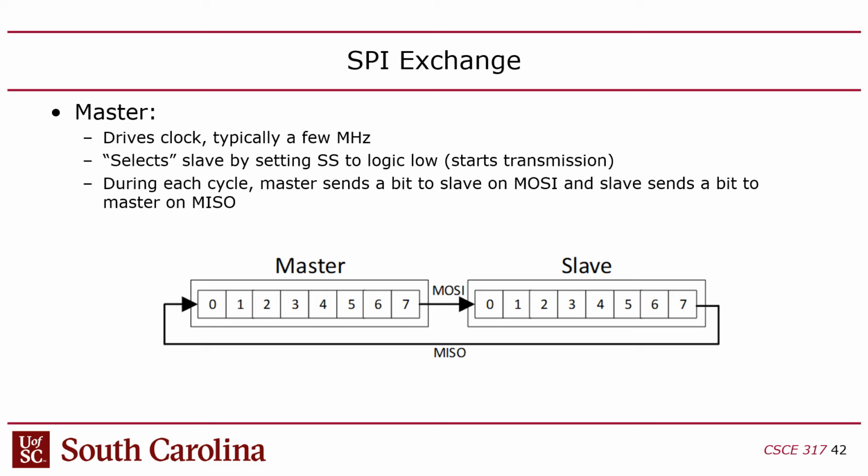Now, ironically, JTAG does use this model, and it's a very similar protocol. And you might say, why are you throwing this stuff out to confuse them? JTAG is what you use when you configure the FPGAs, and it's also a serial bit shift protocol, and you shift all the bits all the way through the FPGA.